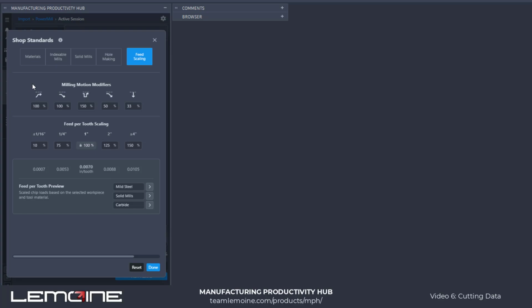So feed scaling is where you've got the opportunity back in Fusion. Do you want to adjust your lead-in percentage feed rate, or lead-out, or transitional, right, or ramp or plunge feed rates? Okay, and then you certainly have a preview here of what we call feed per tooth scaling. So feed per tooth scaling, 7 thousandths per tooth for a 1-inch cutter, but naturally as you use a smaller cutter, you might want to adjust your percentage of that 7 thousandths per tooth. So you'll see it can drop down all the way to 7/10 if you wish.